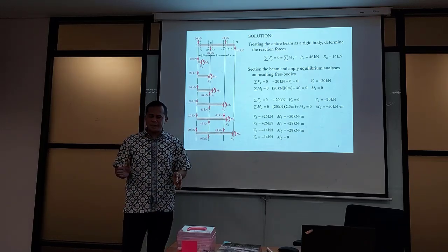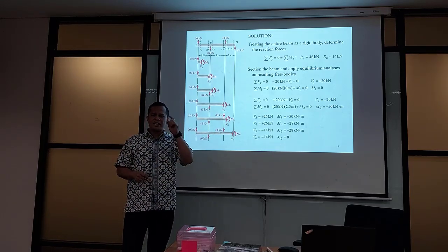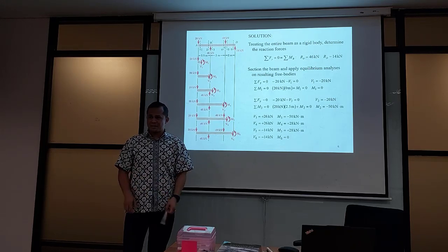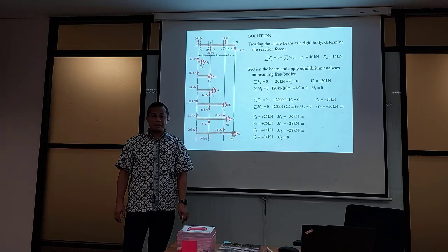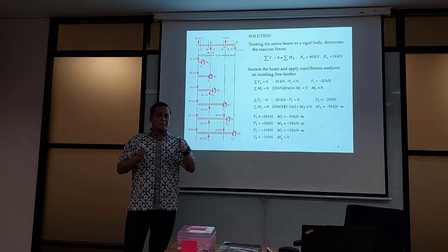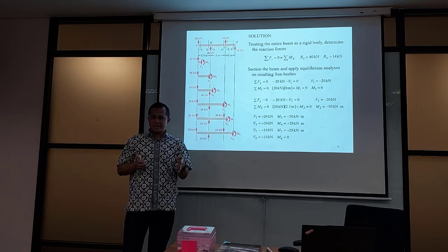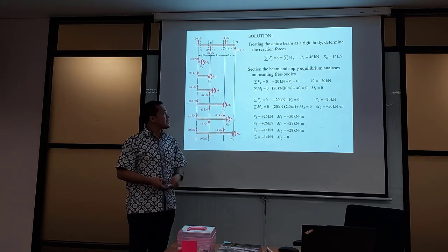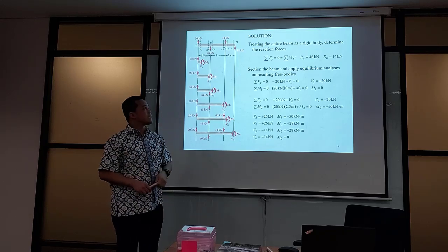What we are going to do is check the value of shear force and bending moment before and after the load. Let me repeat. In order to construct SFD and BMD, we calculate the shear force and bending moment before and after the load. Okay? Now, let's start with number one.